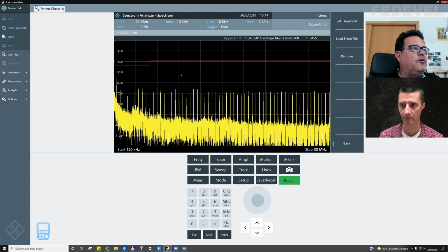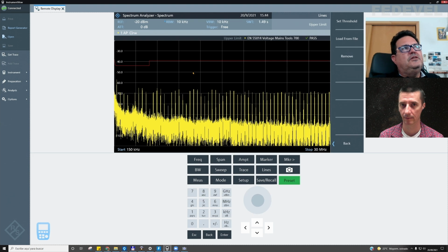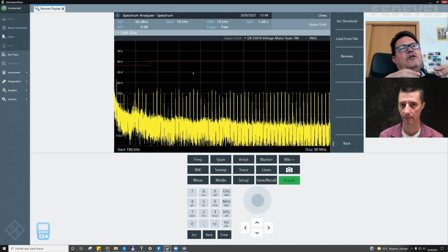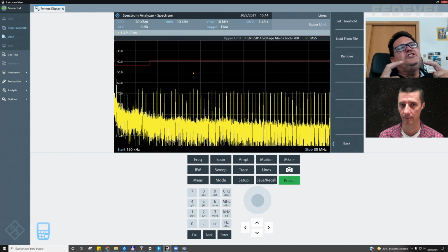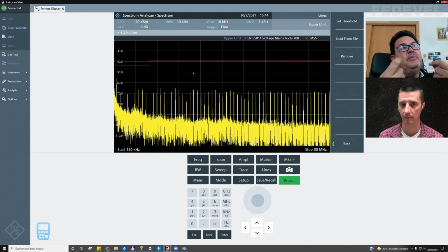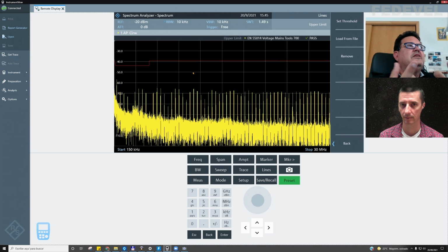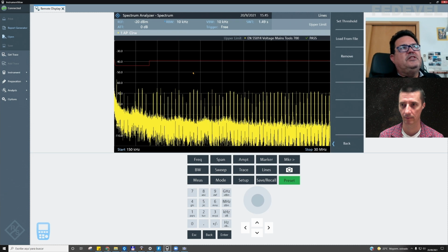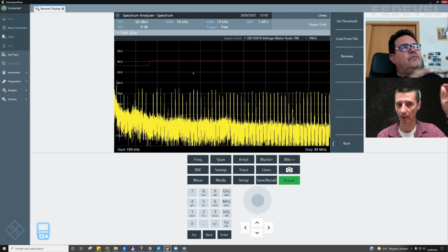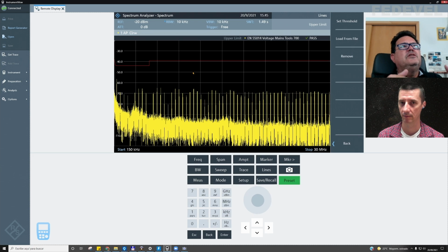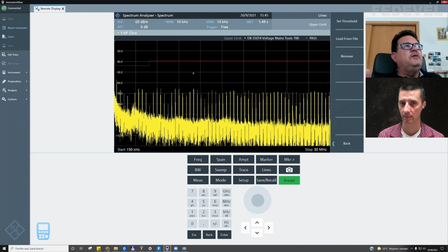So I usually recommend to be below by 10 dBs, no? Or 6 to 10 dBs. Obviously, using a lot of margin is usually more expensive in time and perhaps in cost. You need to analyze, to introduce another component in the filter or something like that. But it depends on the company. 10 dBs from the limit, yeah? From the limit, yes. I like 10 dBs, but usually if you are 6 dBs below the limit, it's a good situation.